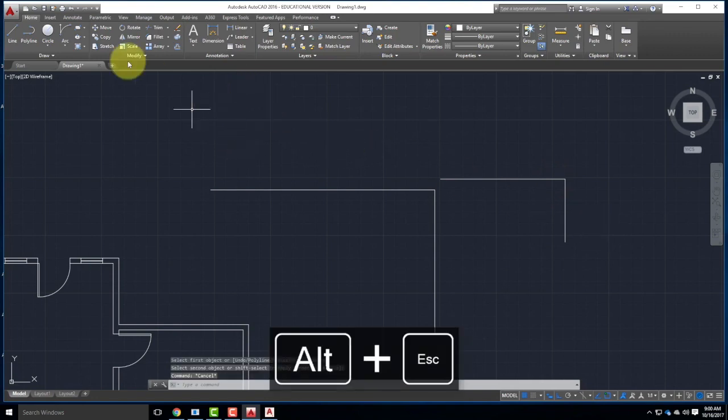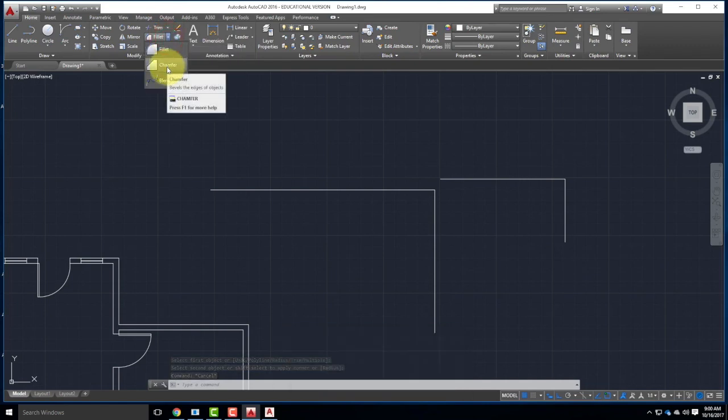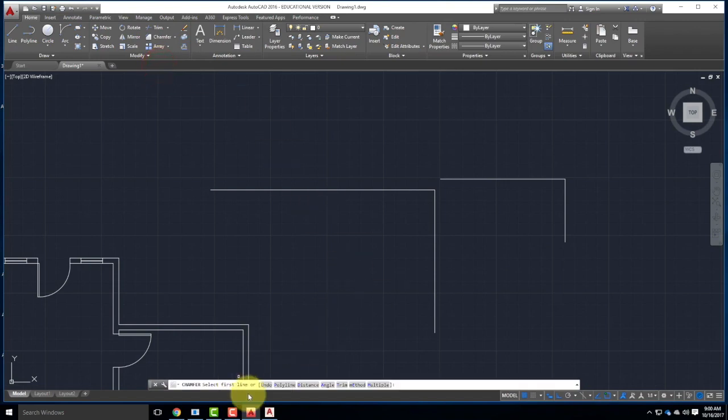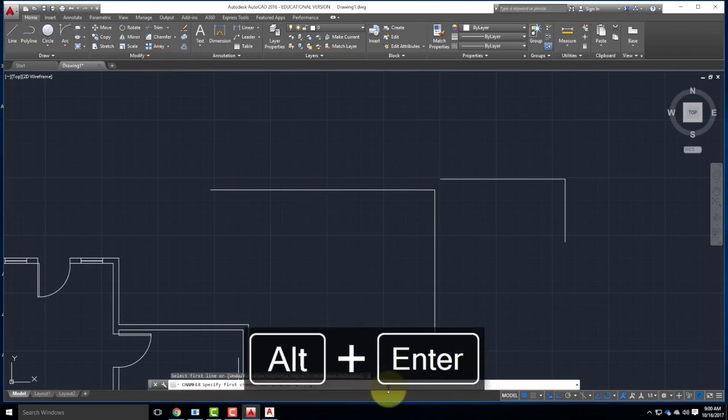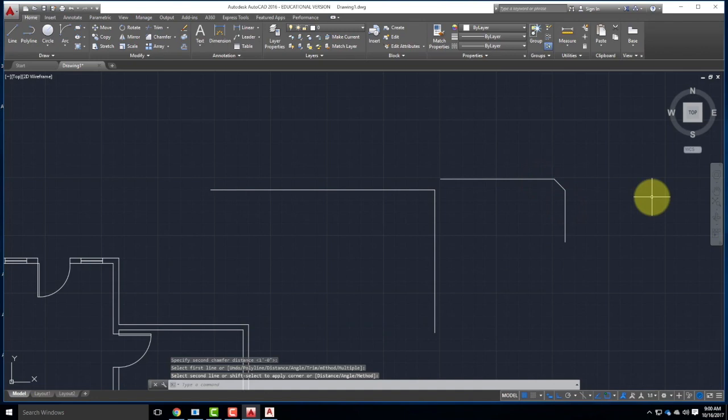Chamfer is similar to a fillet. It's just a straight line instead of an arc. So a chamfer is going to specify distance. If I did 1 foot by 1 foot, we would get these two lines connecting in an angle. It's there if you want it, or if you find it interesting. We did mirror, we did chamfer, we did...